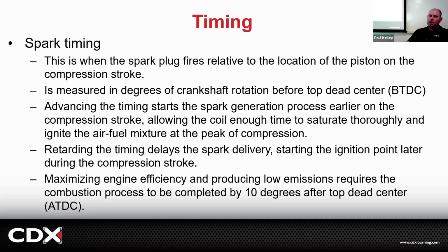That's why timing is always before TDC. But how much before? Well, it depends. If you're going kind of slow, just a little before. But if you're at red line, wide open throttle, your pedals are moving fast, that's the crankshaft, right? So here's your rod coming down. Here's your rod coming up.